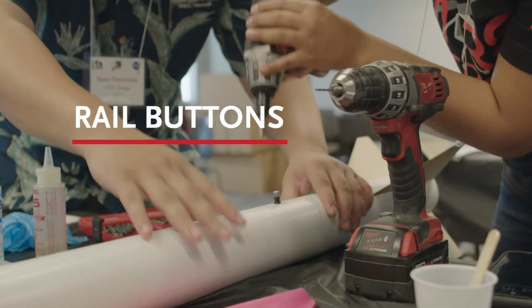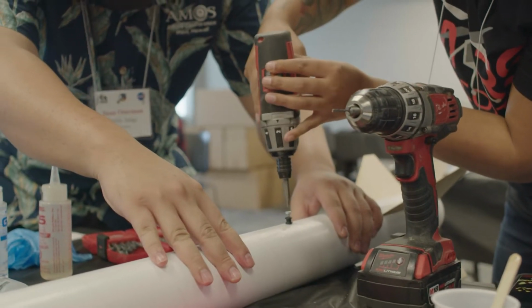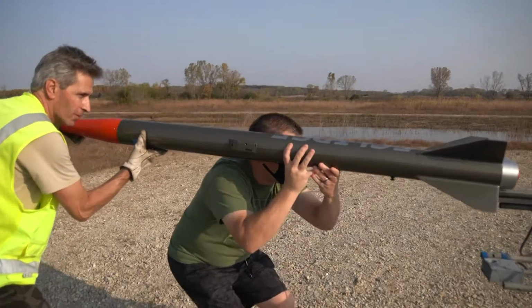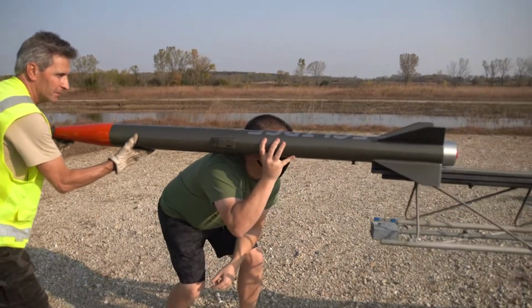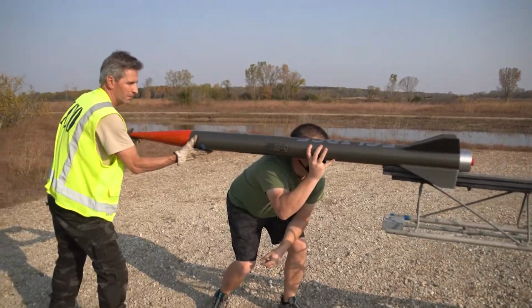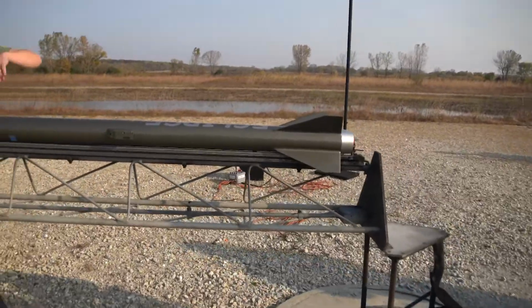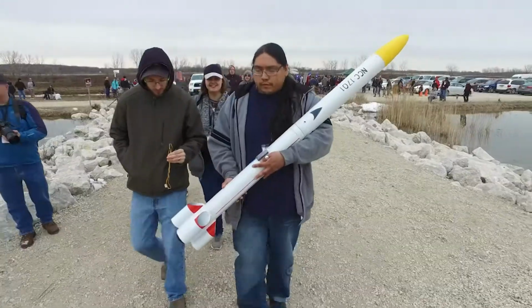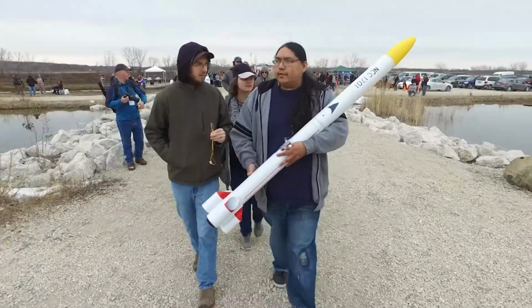A rail button is an H-shaped component made of a hard, smooth plastic or aluminum. These buttons mount to the airframe and slide freely inside a channel on the launch rail. These need to be aligned with the fins and airframe for stability and firmly secured with backing to withstand launch thrust.